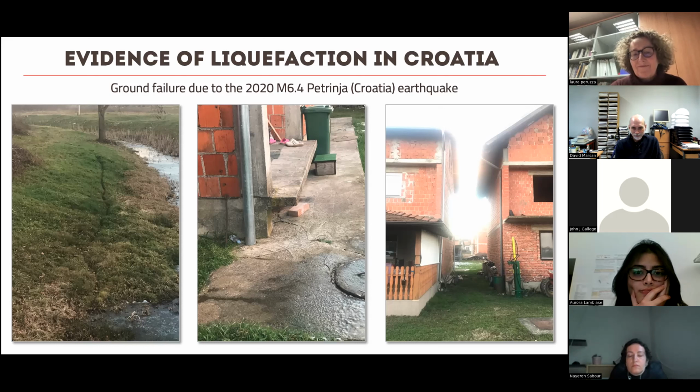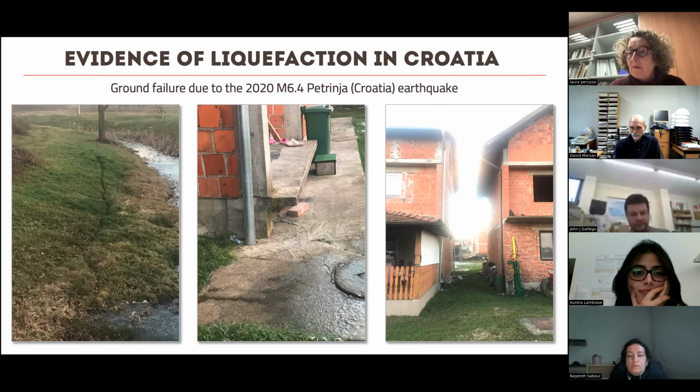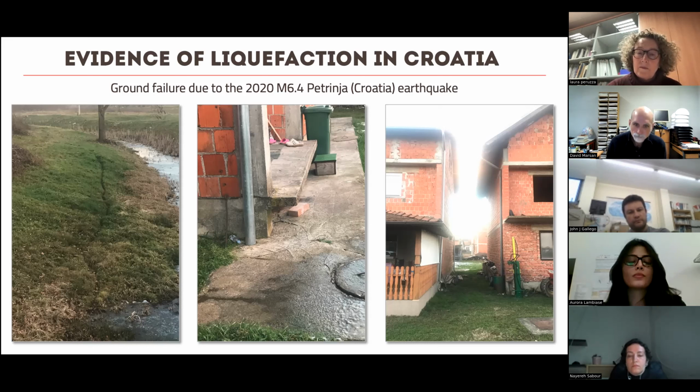Yeah, very much, Laura. So thank you very much for that. And in fact, Julian, who's also here on the call, this is something that worries me a lot, because a lot of the PSHA models provide ground shaking typically on rock, but ground shaking on rock or on bedrock is not very useful for me, because I don't have my buildings on bedrock. I have my buildings on the surface.